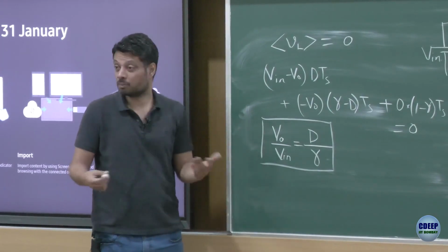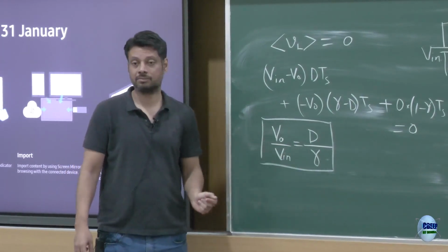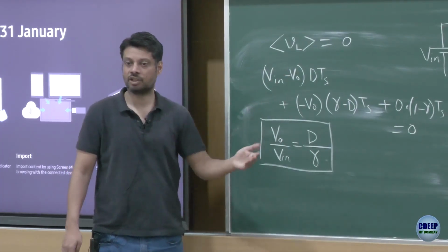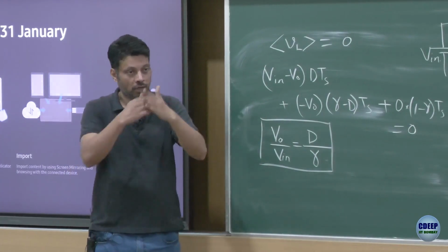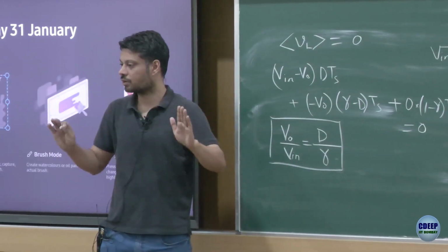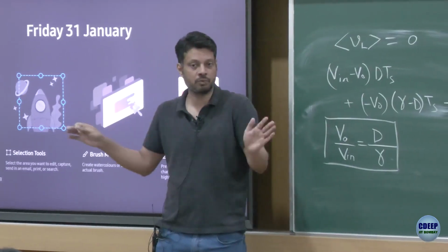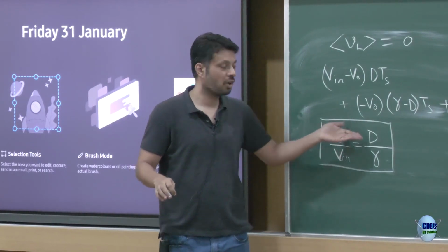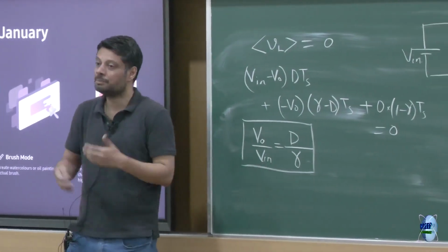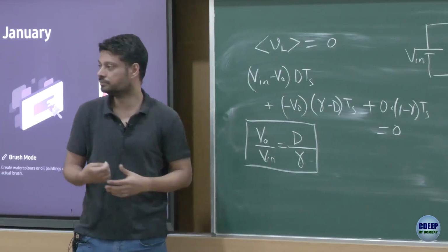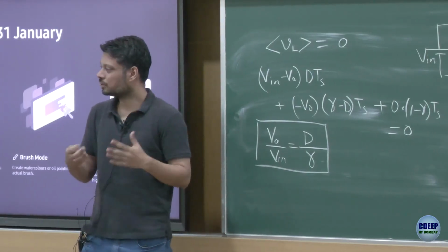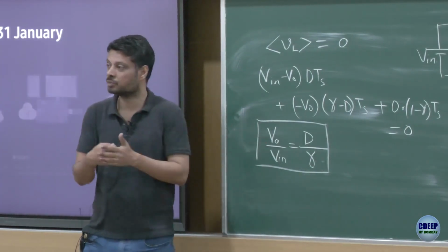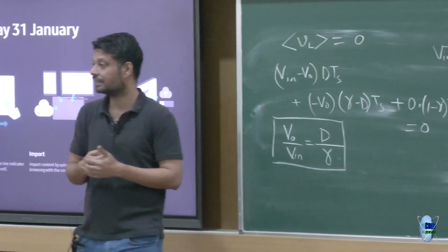And now it's even more difficult because it depends on gamma. So as you go from case 3 to case 4, your gamma will change, your output voltage will change. Throughout CCM, your output voltage was more or less constant, but as soon as you reach DCM, your output voltage is going to change with gamma, and therefore you can no longer maintain a constant duty cycle, you have to keep adapting the duty cycle based on the load, right. Earlier also, in reality, there may be small variations, but not that much, but in discontinuous conduction mode, certainly you would have a large variation of duty cycle, isn't it?